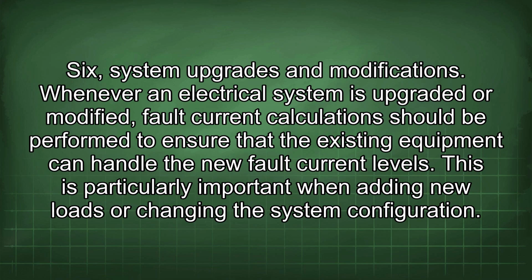6. System upgrades and modifications. Whenever an electrical system is upgraded or modified, fault current calculations should be performed to ensure that the existing equipment can handle the new fault current levels. This is particularly important when adding new loads or changing the system configuration.